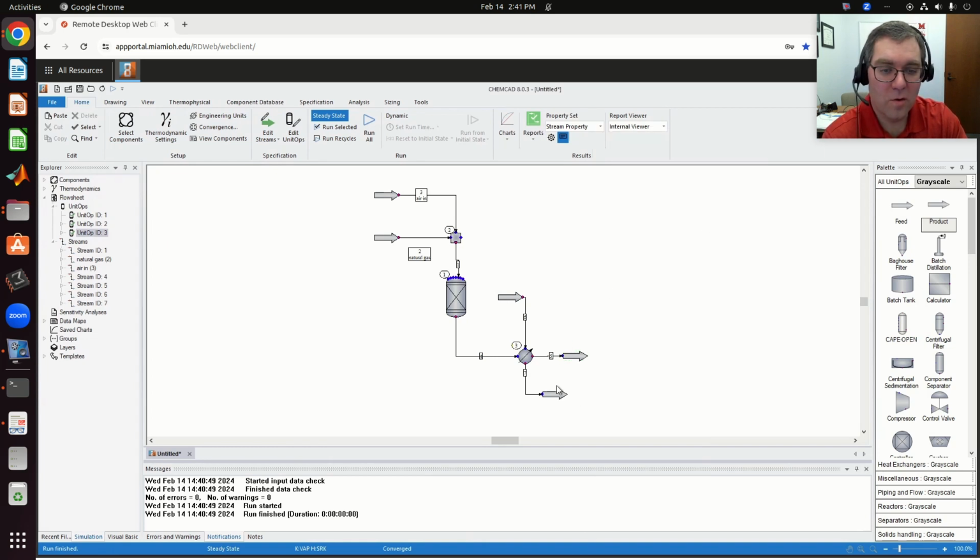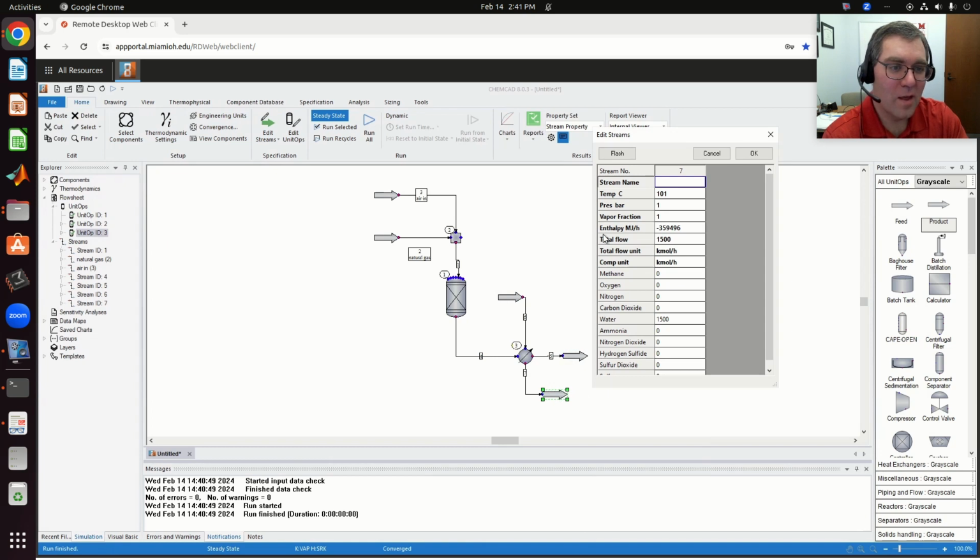So cool. This would then be heat in the form of steam that I could use elsewhere in my plant. So send that to a heat exchanger where I need to heat some inlet liquid up to a higher temperature. Maybe I'm using it to preheat, so we have our stripping column, maybe I would use this to preheat my water going into my plant.